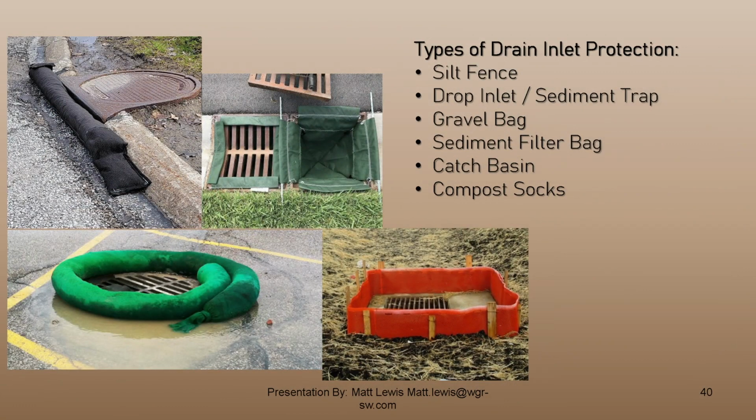You can see the black rock bag there. If you put a compost sock there, you will never have to deal with what most contractors do during a rainstorm. Rock bags are very similar to fiber rolls. They don't allow penetration of water, and it pools up, right? A lot of times you'll see rock bags put around DIs, and they're installed perfectly, but when you come after a storm, or if you're doing a during-storm inspection, they will have kicked the rock bags away from the DIs because you're creating a puddle there, and they say, hey man, you're creating a puddle on site. Come on, we've got to get rid of this water.